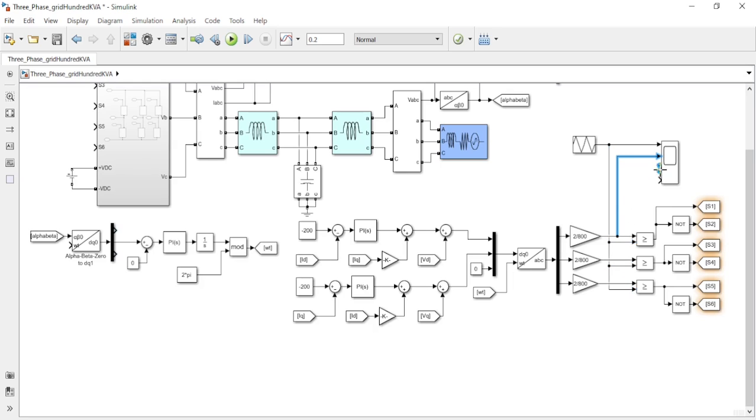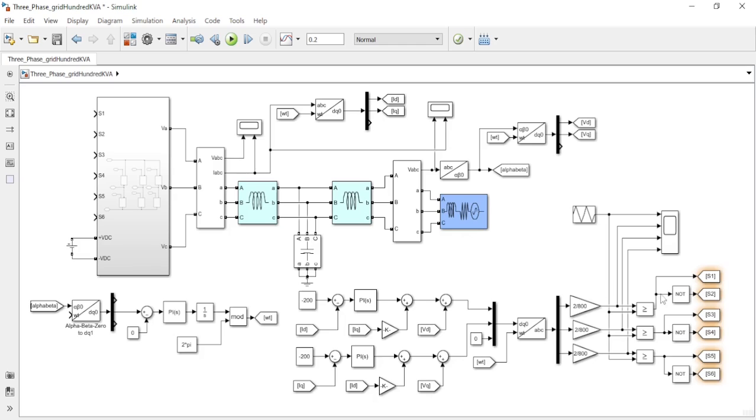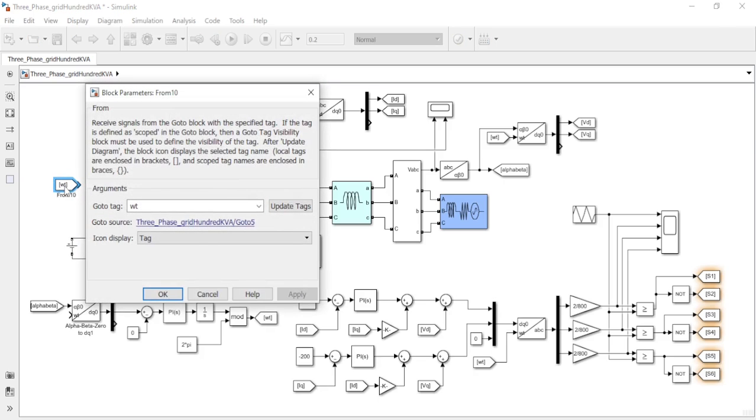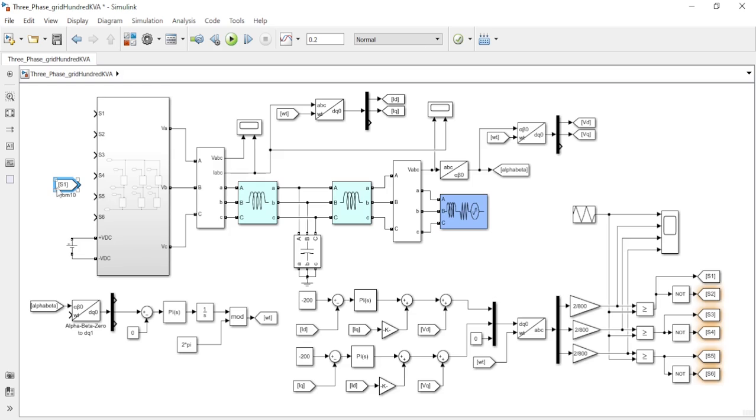Since initially we had 10 kVA, now we have 100 kVA, are these other parameters just going to be multiplied by a factor of 10, such as the filter design? Initially, if you had 10 millihenry as your inverter side inductance, now that you're designing a 100 kVA, are you going to have 100 millihenry for the filter, and is the system going to still work the same?